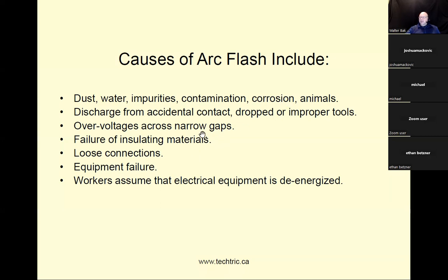Overvoltage across narrow gaps. Well, when you were doing your labs on your breadboards, you are using 5 volts, 10 volts, 12 volts on your breadboards. So if you have the two terminals and they're close to each other, 5 volts is not going to cause an arc flash. However, if you have thousands of volts, then the air comes into play, because air does have certain resistance, which means it is not infinite resistance.